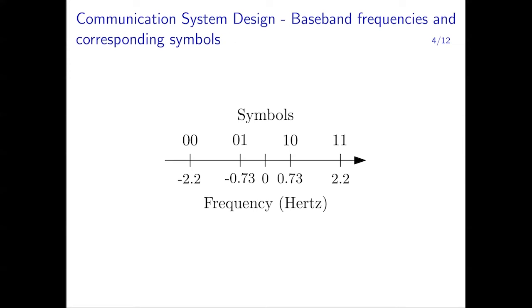So we have a 2-layer protocol, physical and frame layers. I'll say a few words about the physical layer first. One of the constraints that we have, we operate at very low frequencies, and this makes possible long-distance propagation. Now at low frequency, we have very narrow half-power bandwidth. So it means the signal must be very narrow bandwidth. Actually, ours is only 4.4 Hertz.